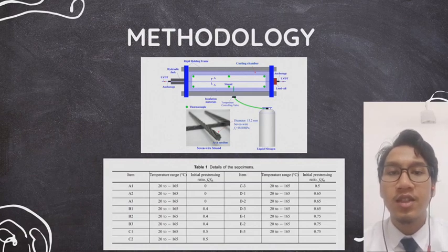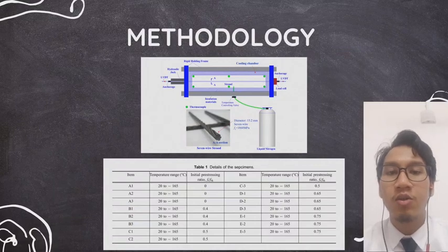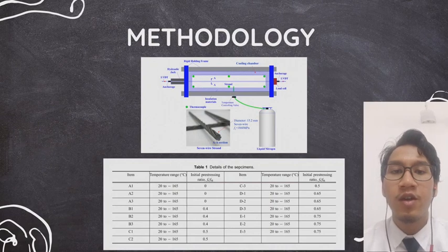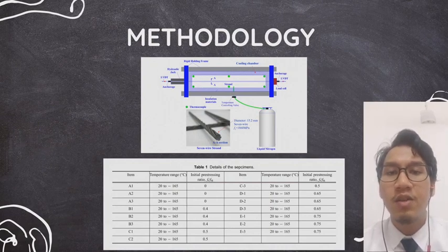Liquid nitrogen was injected into the cooling chamber through an electromagnetic valve to achieve the low temperature environment. Insulation measures were taken to cover the cooling chamber to isolate the heat transfer from the environment to the cooling chamber. Since the pre-stressing level would influence the thermal expansion coefficient of the steel strand, a hydraulic jack was used to pre-stress the strand in the cooling chamber.